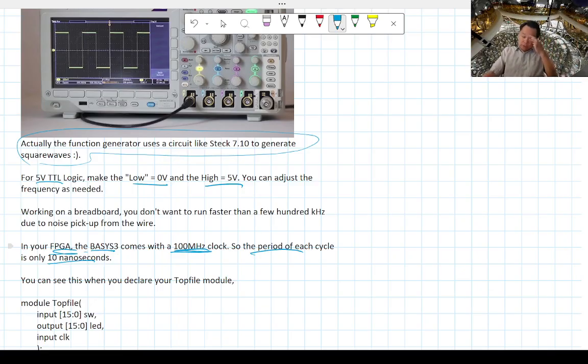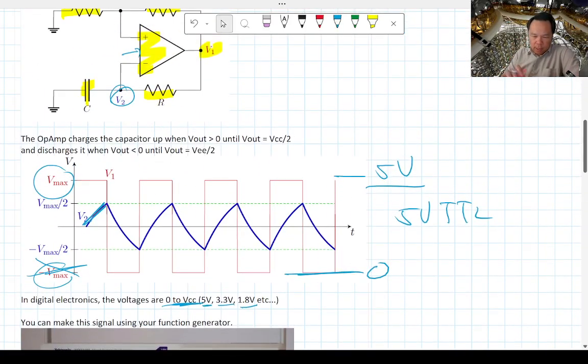So let's say you're building a computer or something like that, inside that computer there's probably a couple of feet of wiring. So if you're running at anything above 200 megahertz, they'll get out of sync, and you can't change that yourself. If the manufacturer tried to set that much higher, let's say I want a 1 gigahertz clock speed computer, you can't do that, because the wiring will just have a propagation delay. Okay, so that's how you actually build a clock on a breadboard.